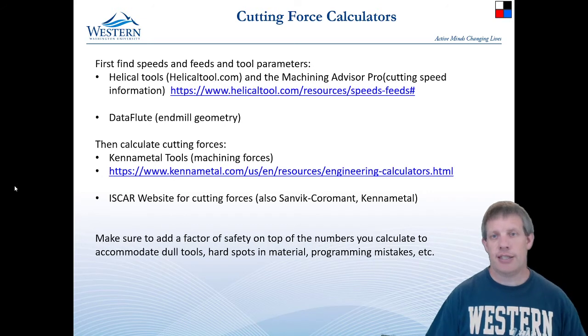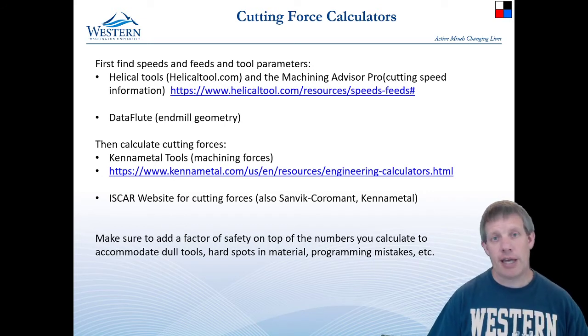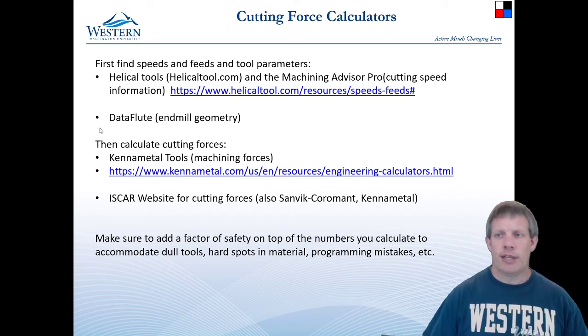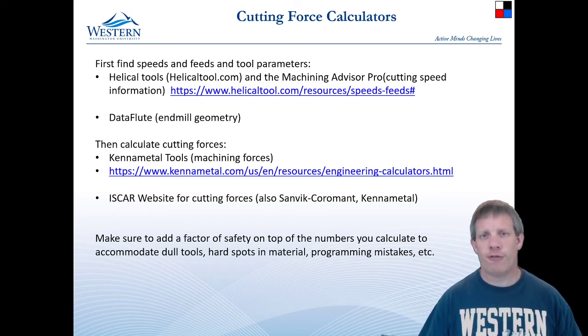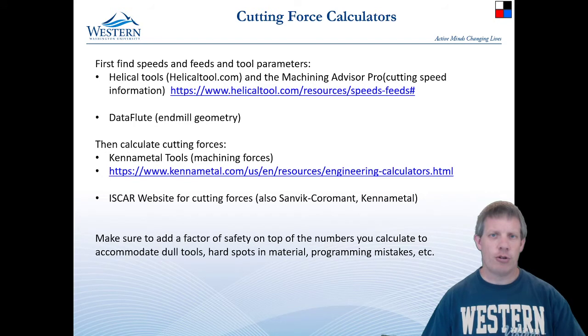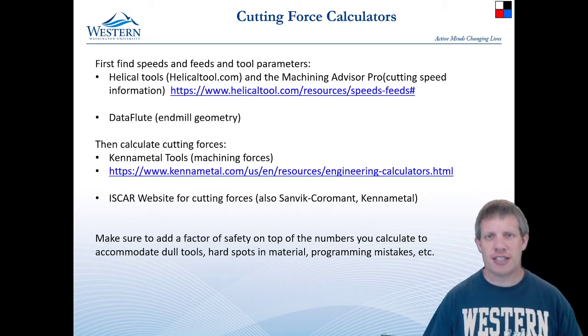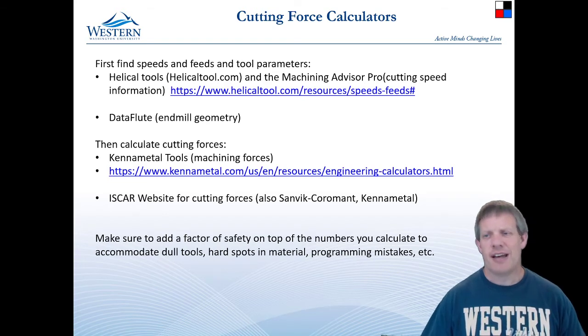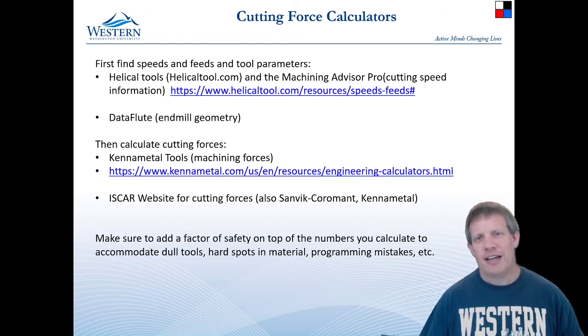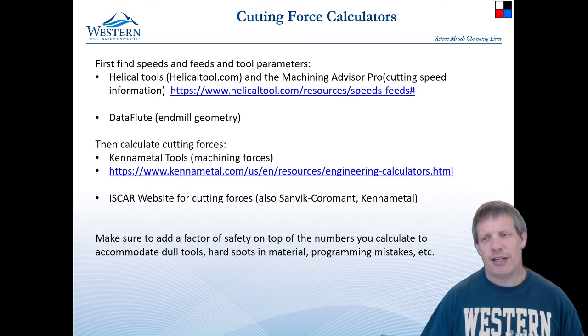Then after you've done that, we need to go to one of the other cutting force calculators, and those typically are not the same as the cutting feeds and speeds calculators. Kennametal has a really good one, though it is not their first priority to keep this running. Over the 6 years that I've taught this class, I would say that this calculator has been running for 4 of those years, and 2 of those years it was broken for the entire quarter and never worked. So you should always have another cutting force calculator in your back pocket.